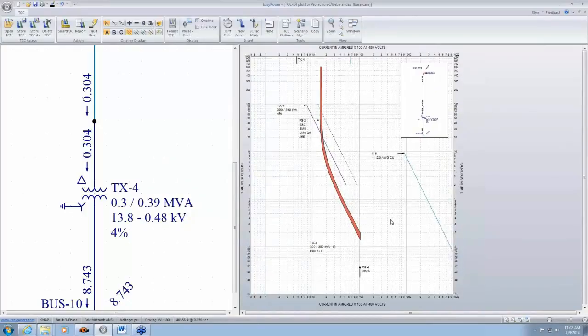So another point to look at is when you select fuses or any circuit breakers or any protective devices, we need to make sure that the inrush current is on the left side or below the tripping curve. If the trip device is faster than this inrush point here, then you'll get nuisance tripping upon energizing the transformer, and we need to avoid going into that nuisance trip condition. So in this case, the fuse is taking longer time to melt than the inrush time here. So I think it's doing a good job of protecting this transformer and allowing the inrush current to pass through as well.